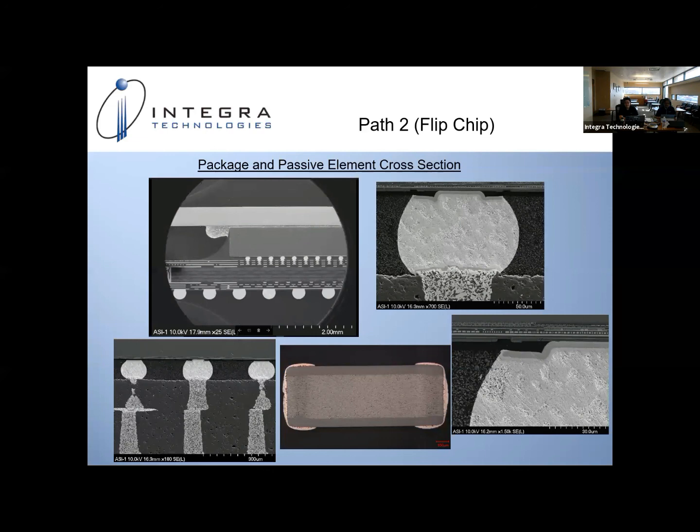It is good to look at the internal structure and the alignment of those internal solder bumps, because after all, it is what powers on the chip. Obviously, the external bumps too. But also in cross-section, after delid, you could pull off the capacitors and do a cross-section on those, and do inspections to EIA 469, because those are all part of the DPA for a flip chip, or at least we think that it should be.